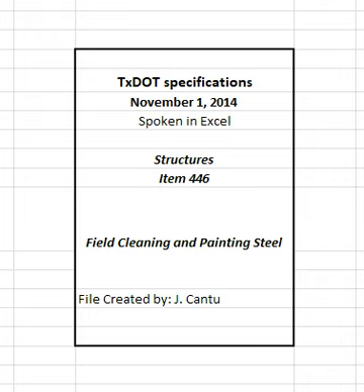Apply sprayed coatings essentially 90 degrees to the surface and between 10 and 18 inches from the surface as necessary to apply a full wet coat of paint free of overspray, runs, sags, and holidays. Any spray painter who does not consistently spray in this manner or extends the spraying stroke so paint is applied to the surface at an angle of less than 80 degrees will not be allowed to spray paint. Brush application for touch-up is acceptable as long as the paint is mixed in the appropriate proportions by weight and is agitated continuously during the painting operation.